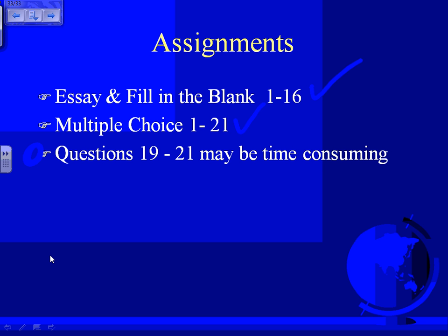Since we're going to be doing it for our project, I don't want to overwhelm you. So what you're supposed to do is go to the end of the book, right here, and pick, if you have a 4x4, you have only one of them, go find the cost for it from the end of the book. Can you guys see that? And then extend it, so whatever that cost is gets multiplied by 1. And then how much labor for a 4x4? You're going to get the labor unit. Where do you get the labor unit from? From the back of the book.